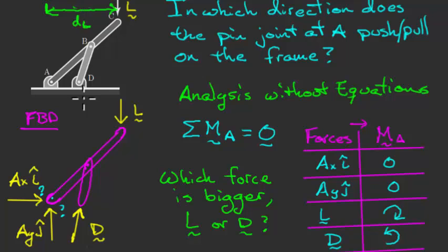There's the moment arm. For the force at D, it's acting right here at point D, producing a force up and to the right. And what is its moment arm? Its moment arm, well, you just extend this rod down, it's this perpendicular distance right there. Right? Can you see that in there? I'll call it DD. There's the moment arm for force D. And what can you say about this moment arm compared to that moment arm, right? This moment arm down here is about half as big as the moment arm up there, right? We have half as much leverage.